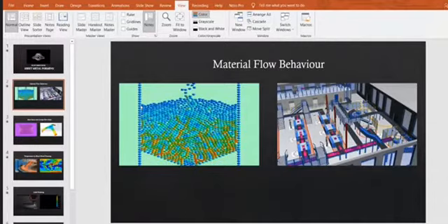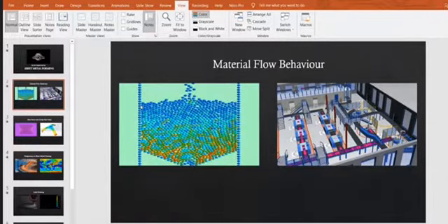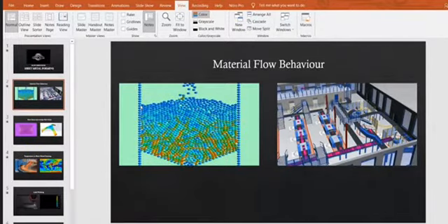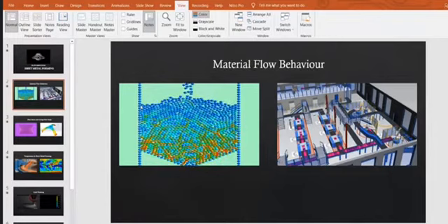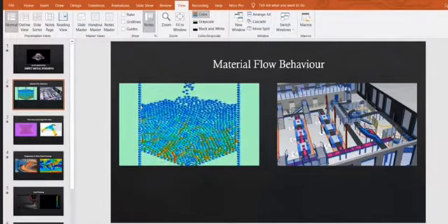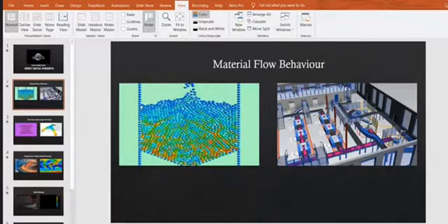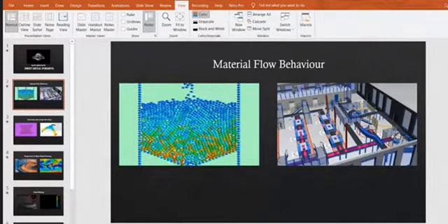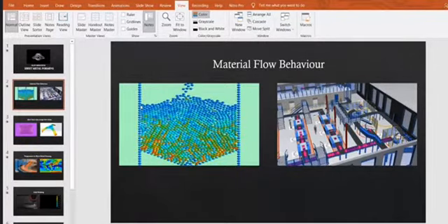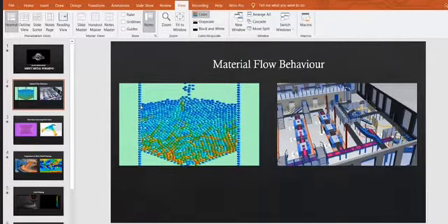In the plastic region, the metal's behavior is expressed by the flow curve. Sigma is equal to K epsilon to the power n, where K is the strength coefficient, with MPa as its unit, and n is the strain hardening exponent. The stress and strain in the flow curve are true stress and true strain. The flow curve is generally valued as a relationship that defines a metal's plastic behavior in cold working.